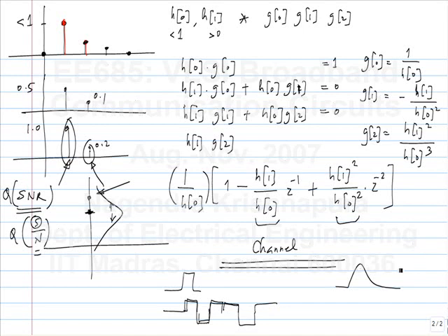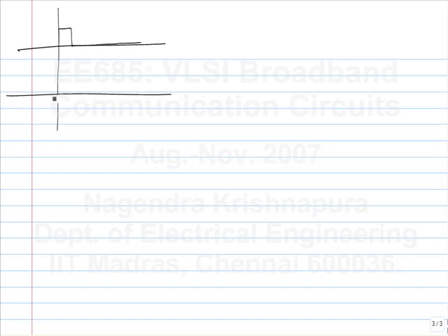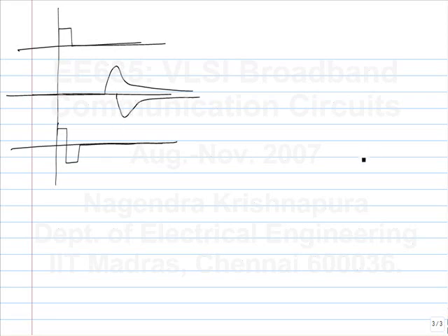So maybe if the channel has a delay, which is I think what you are thinking about. You have a transmission line which has some delay, so the response to a single pulse may be something like this, with a delay. Then if I want the response to a 1 minus 1 sequence, I take this, shift it by 1 bit interval, flip it and add it.